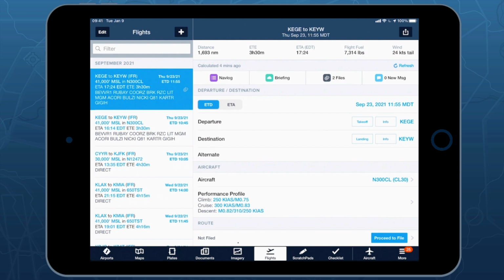We've shown a little bit how the three components of weight and balance, runway analysis, and flight planning all talk to each other. If you're out of CG on the weight and balance side, it's going to communicate that back to flights, and you have to make sure you get within CG. Same with any kind of weight checks and fuel checks for that matter as well. So this kind of covers the entire section of runway analysis and weight and balance, and I think I'm going to pass it back to you, Sam.